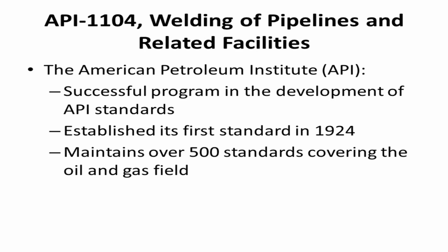Okay, the API Standard 1104 details the welder and weld qualifications for welding of pipelines and petrochemical facilities like pump stations and refineries, etc. There's an interesting field testing method in API. In the API standard, it uses a nick break to test weld quality. There's no tensile or bend test when you're out in the field. So it's kind of interesting that they do that.